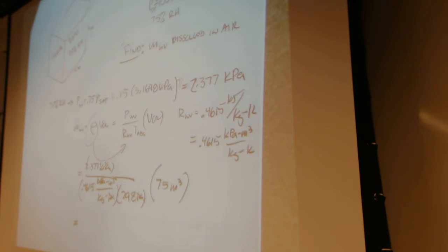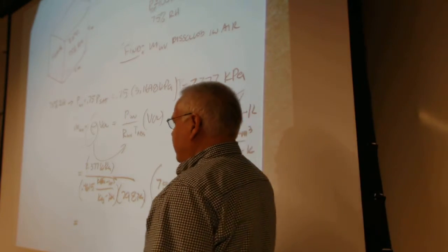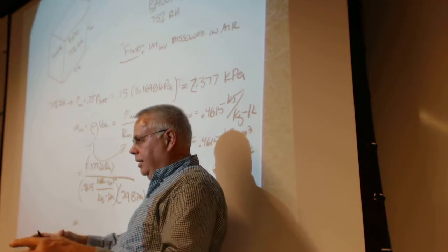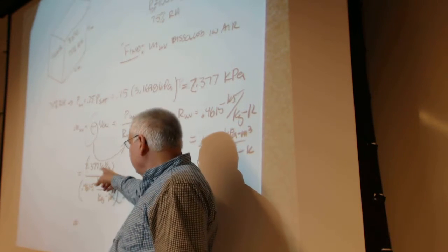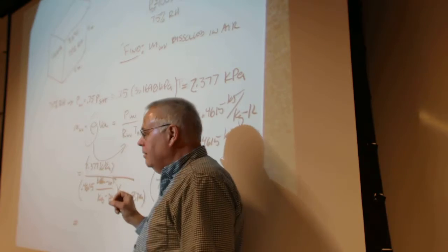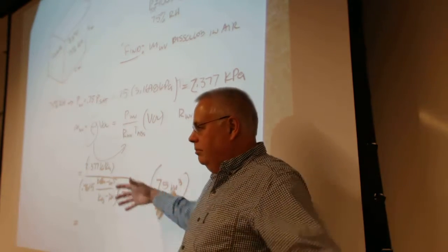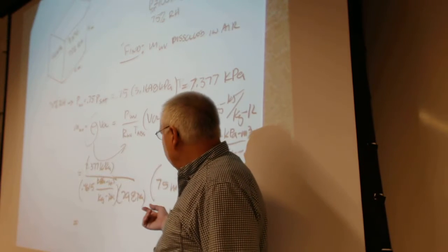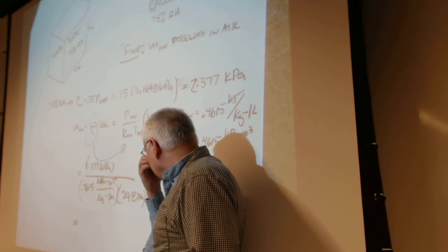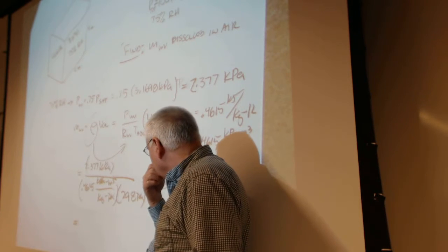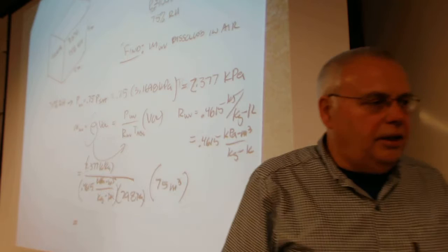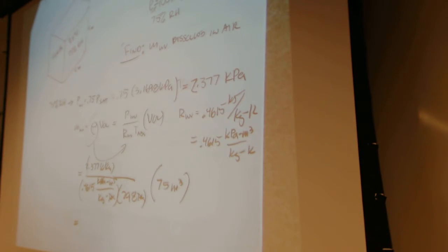We've got the density of the water vapor in the air at its partial pressure, and its partial pressure is this much, times the volume in the room. So that should get us what? Meters cubed, we're going to cancel, end up with kilograms. We are 1.296.